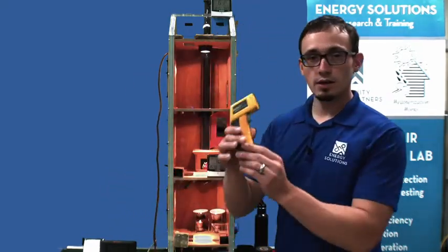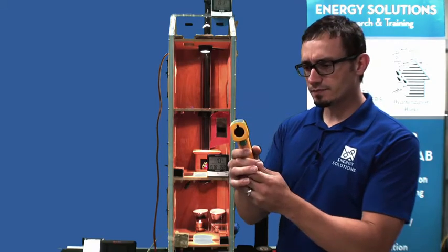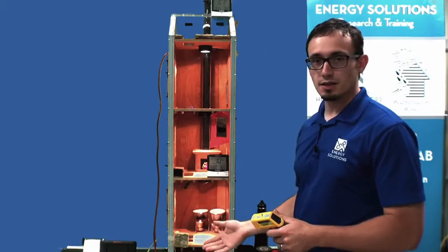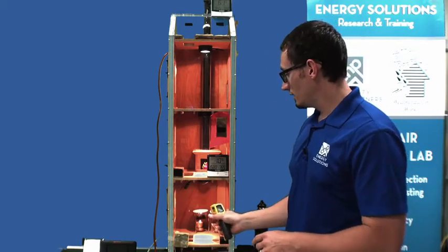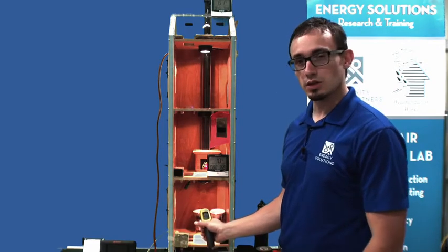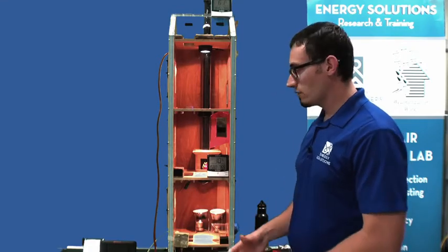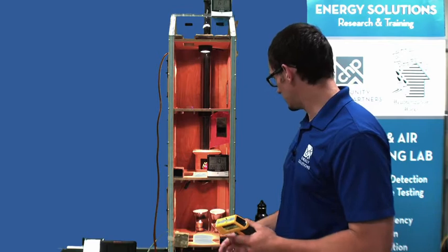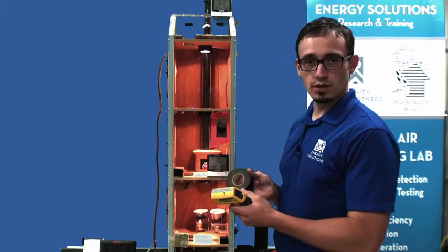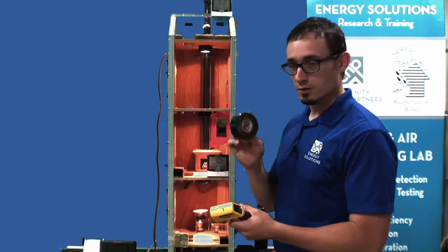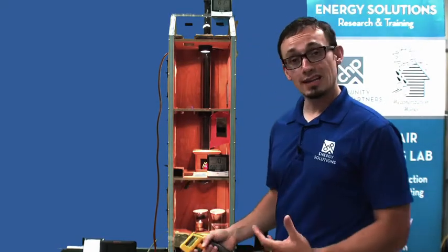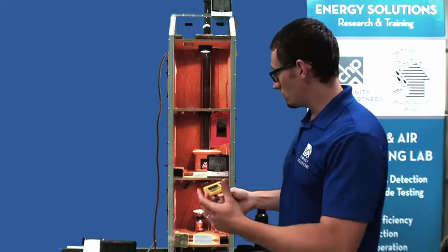So if I incorporate a little help here, I've got my spot infrared thermometer. I want to keep that nice and close to the building. And then I've got some clear plexiglass here, and that's really not going to be too great to get measurements for, because it's going to say I've got a 120 degree surface temperature, which is not quite accurate. So we've got some really high dollar, really expensive stuff. What is this called again? Vinyl electrical tape. Yeah, really high dollar stuff here, attached on the plexiglass, so I'm going to be able to take surface measurements and see where we're at.